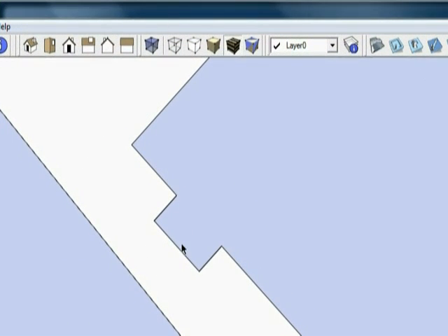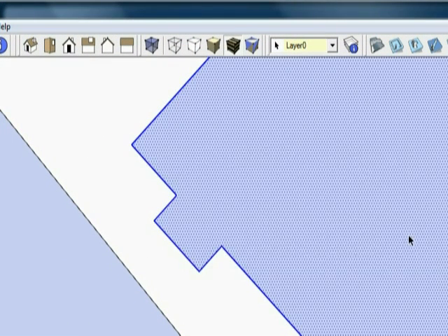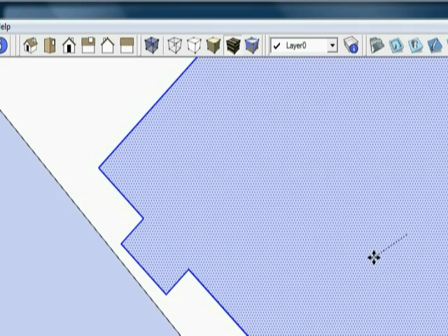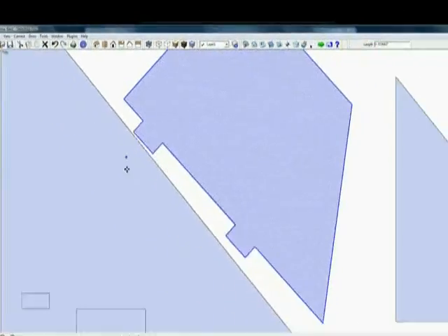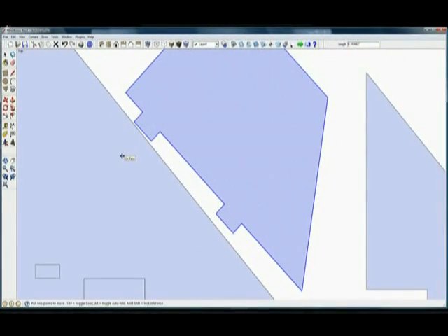So we don't want to have it so, if I were to move this part just to demonstrate, if we were too close, then maybe by the time that bit cuts all around, it's going to cut into this part and it's going to yield a poorly cut part. It's not going to be accurate. It's not going to be correct. I'm going to hit Control Z to move that back.